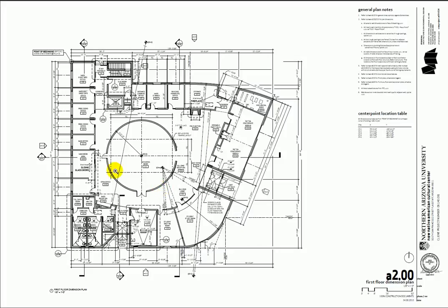So this is where, unfortunately, the structural contractors, the foundation contractors, are going to have to come here to lay out their building. I see a few things here. I see all these dimensions. I see this point of beginning. So basically this is the reference point for the whole building. Everything's referenced to that point.